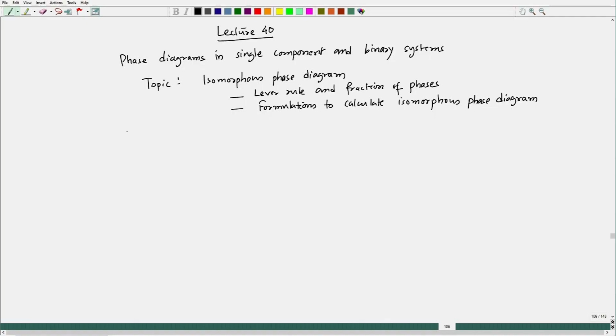And the experiment we need to carry out is basically called differential scanning calorimetry or DSC. From that we can get melting point information of both the pure components, as well as the enthalpy of melting for both the pure components. So, these two pieces of information will be required to draw a complete isomorphous phase diagram. So, that will start today. But let us see what diagram we got. Remember, we will keep our assumption that the melting point of B is always more than the melting point of A for our entire discussion.